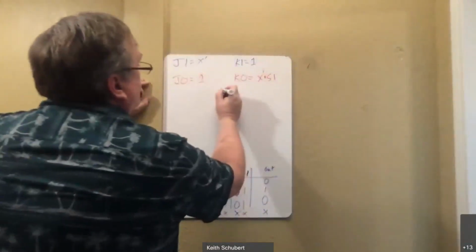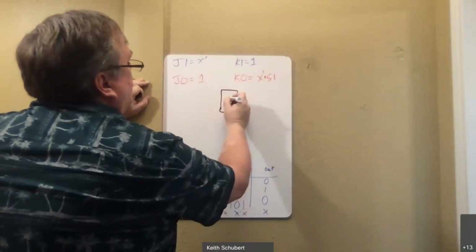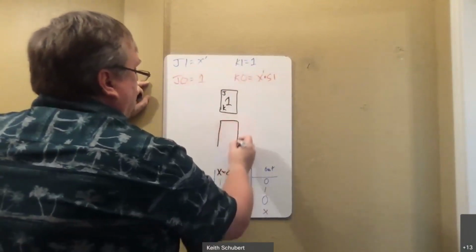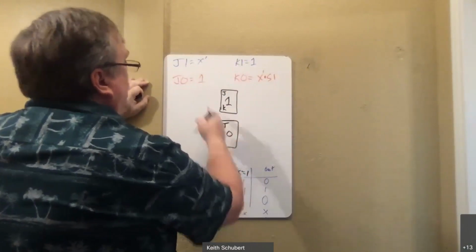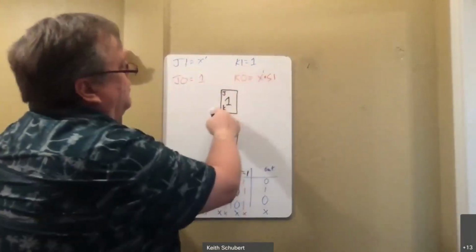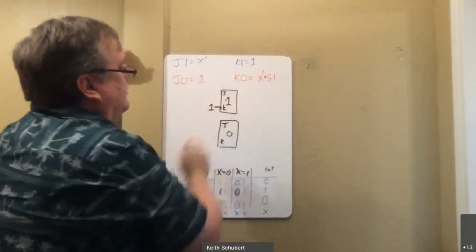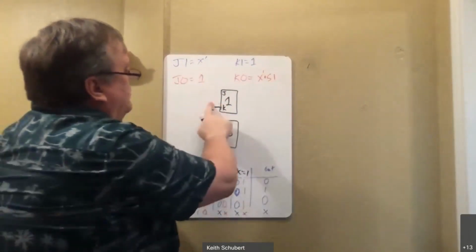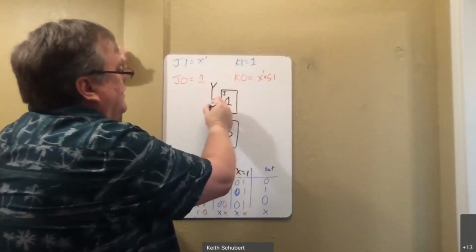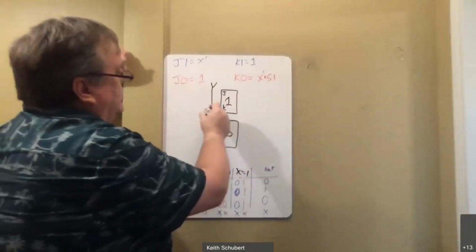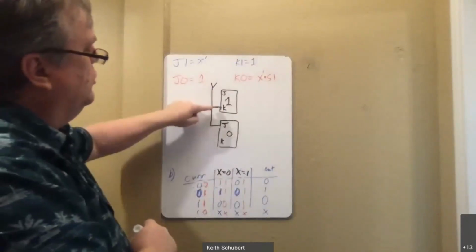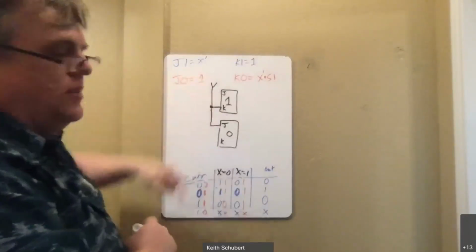So I know I have 2 flip-flops. I have flip-flop number 1 that has a J and a K input. That's this. And I have flip-flop 0, which has a J and a K input. That's described by these. I'm going to do the easy things. The K input for number 1 is equal to 1. You can also do that as power if you want. Typical way we show power is to just put that and run down. J0 also gets a 1 or power. You can either put a little line with 1s, or you could connect to the power line, whichever one makes you happy.